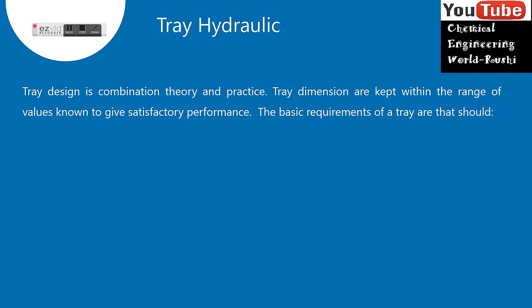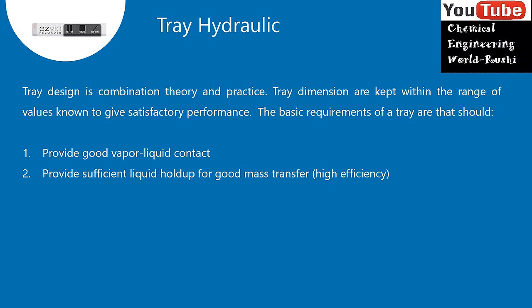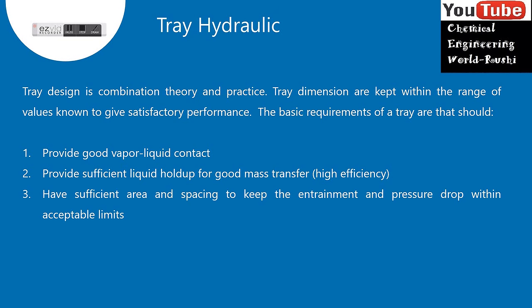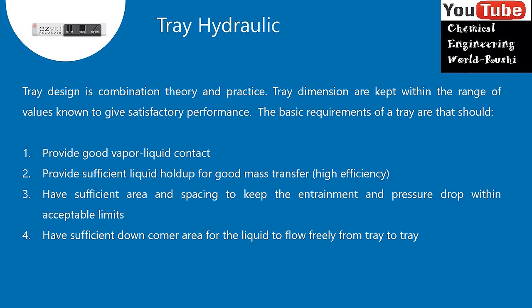1. Provide good vapor-liquid contact. 2. Provide sufficient liquid hold-up for good mass transfer, high efficiency. 3. Have sufficient area and spacing to keep the entrainment and pressure drop within acceptable limits. 4. Have sufficient downcomer area for the liquid to flow freely from tray to tray.